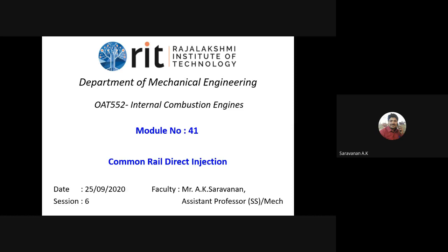So the common rail is a fuel injection system used in diesel engines, and it basically works as a synchronized injection via the common passage, the common pipe, right? Compared to conventional diesel injection systems, it is a superior system for fuel consumption, exhaust gas emission and noise reduction, right? So these terms are superior in CRDI engines.